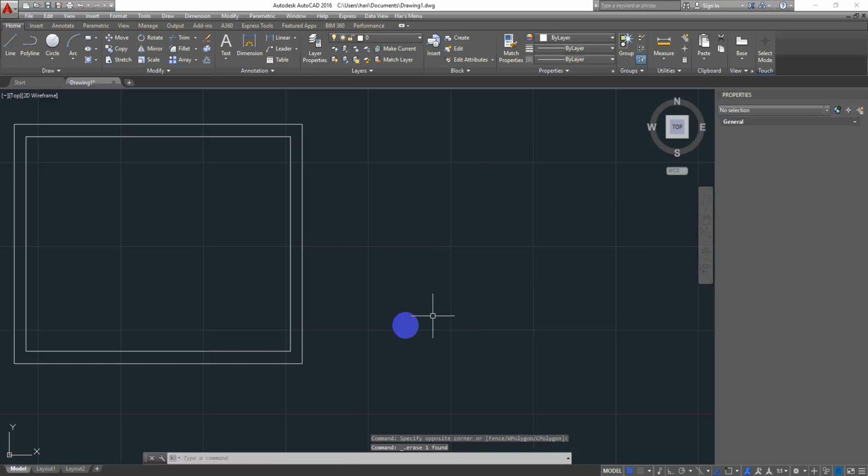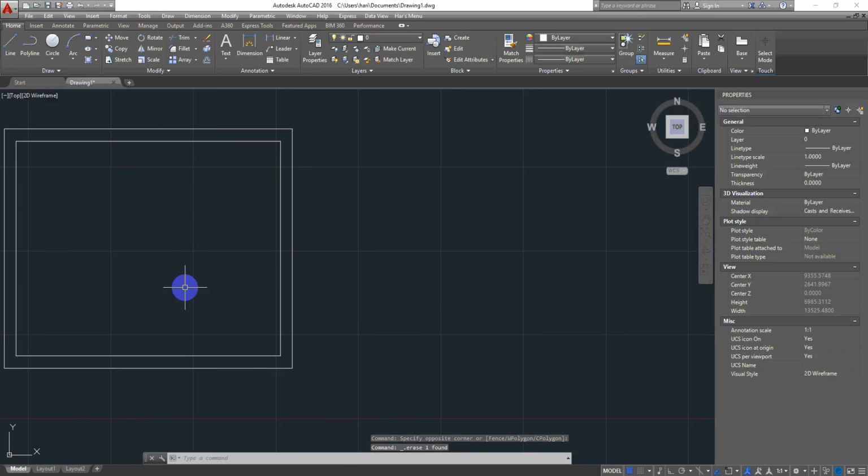So if you have a regular room, a rectangular or a square room, then you can easily use a dynamic block for placing that text here, which reads the length of the room and the width of the room. And as you change that block based on the width and length of the room, this text also will update. Let us look at how to create it.